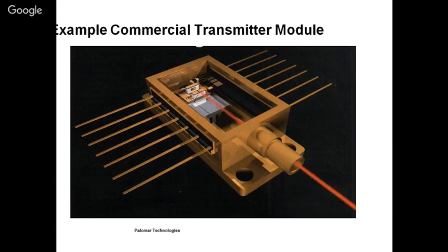If over a period of time the intensity goes down, all light sources, intensity goes down over a period of time. If you have your LED bulb, or even if you have your tube light or even a tungsten lamp, over a period of time the intensity goes down. Similarly, in case of lasers or LEDs also, it goes down. But we know that if we increase the current, then once again the illumination will be restored. So we have a photodiode which senses the light, and if it goes down, it increases the current. That also is inbuilt into this very module.